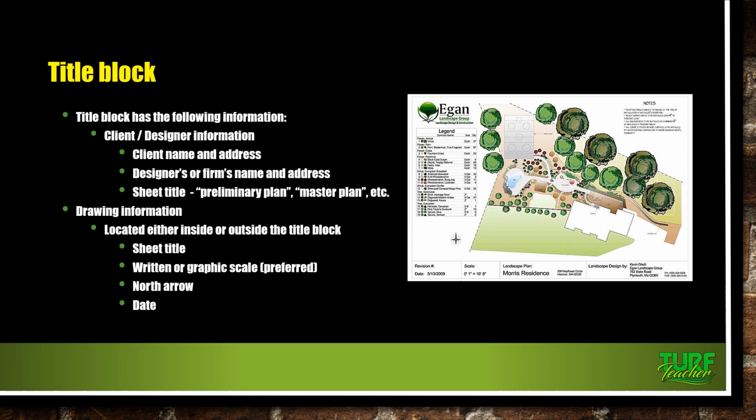And then the drawing information located either inside or outside the title block, which will have the sheet title, sheet 1 of 4, 1 of 1, whatever it is, written or graphic scale preferred, and then the north arrow, and then a date that the design was done.